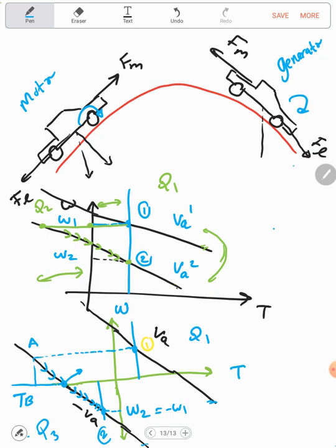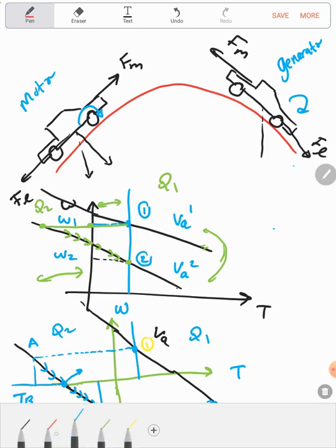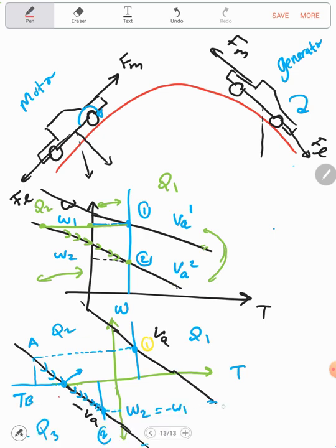This is also I will go from Q1 to Q3 via Q2. The same thing is applicable if I need to go from Q3 to Q1. So the same thing here, I will follow this line. After that, I will decelerate until crossing the zero, then I will accelerate. In this case, I'm going from Q3 to Q1 via Q2. So also, I'm entering the regenerative braking.